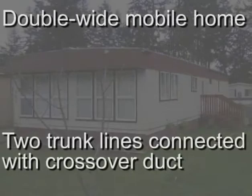In a double wide mobile home, we actually have another trunk line on the other side of the mobile home. That needs to be connected in order to have conditioned air flow between both sides of the mobile home. And that connection is called a crossover duct. Occasionally we'll find more than one crossover duct under a mobile home.